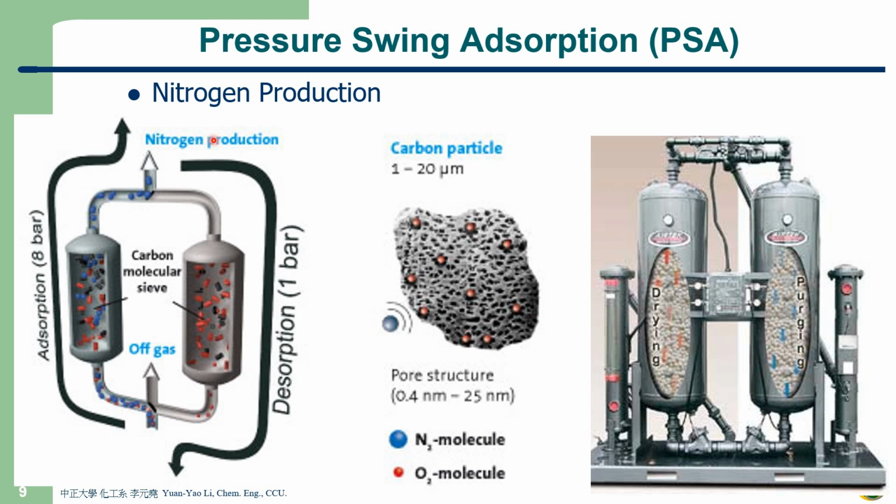And you might have a question, say, oh, Professor, if the oxygen was trapped into this column, how can I remove this? So another step is called desorption. This is adsorption, and this is called desorption. So you do the desorption by energy, for example, by the temperature or by the pressure. So oxygen will come out this way.